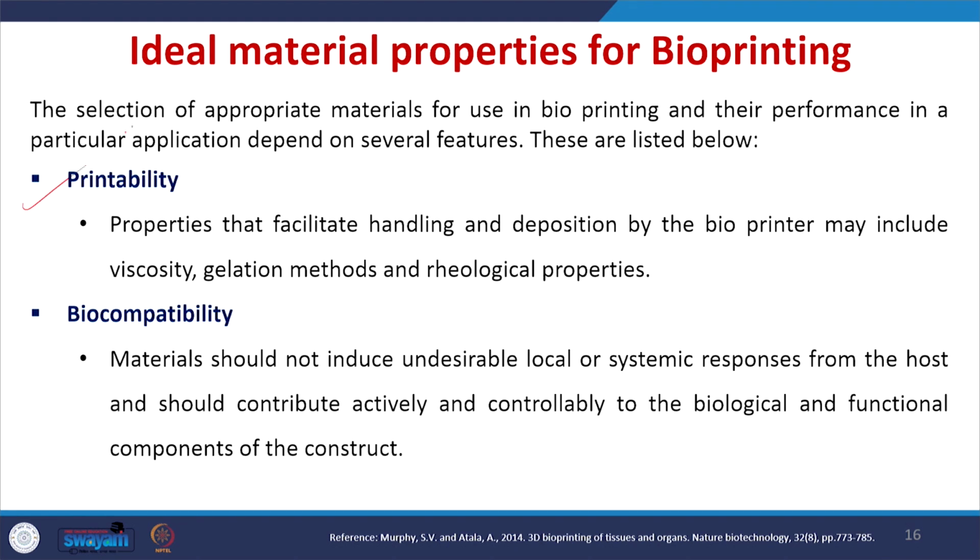The first one is printability. The material should be printable, and that depends on the viscosity, gelation methods and rheological properties of the particular material. And the material should be biocompatible in nature. That means it should not induce any adverse effects in the body. So, it should be compatible with the biological system.